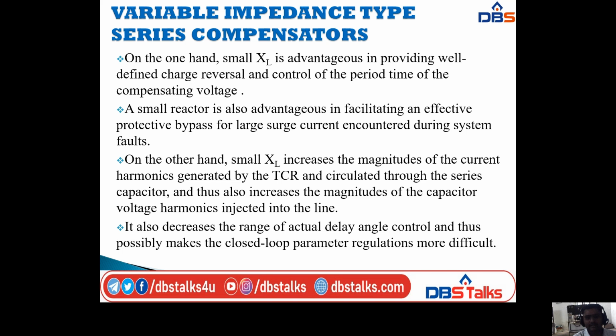A small reactor is also advantageous in facilitating an effective protective bypass for large surge currents encountered during system faults. On the other hand, a small XL increases the magnitudes of the current harmonics generated by the TCR and circulated through the series capacitor, and thus also increases the magnitudes of the capacitor voltage harmonics injected into the line.